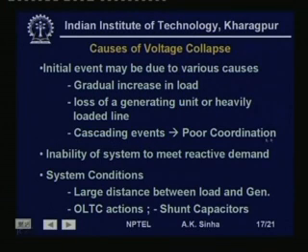So, load demand will increase, which will mean further increase in the reactive power demand, and thereby reducing the voltage further, and this kind of a situation can lead to a runaway condition where the system loses stability or the load will be lost. So, a poor coordination of control events can lead to further cascading events.